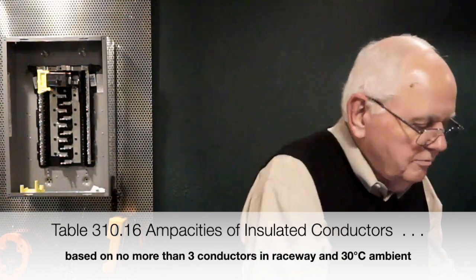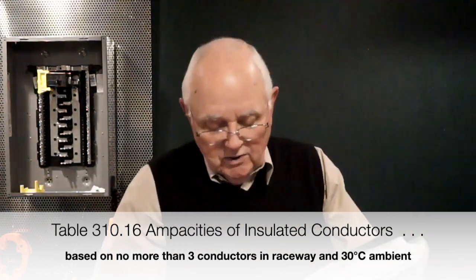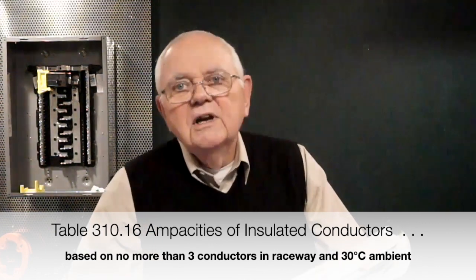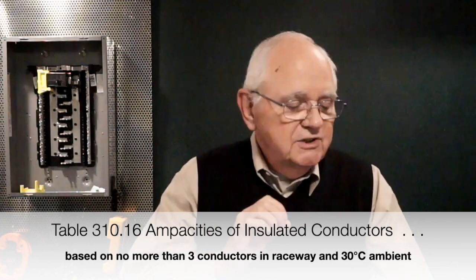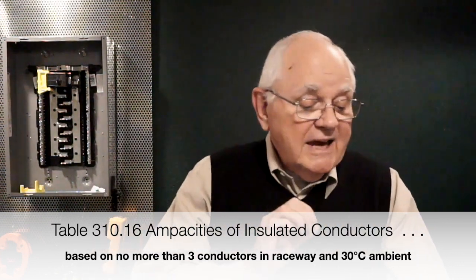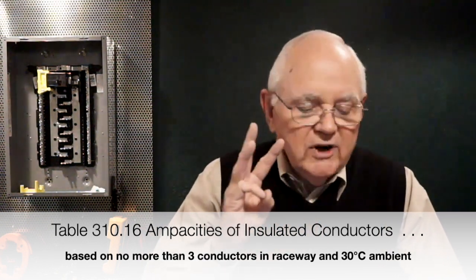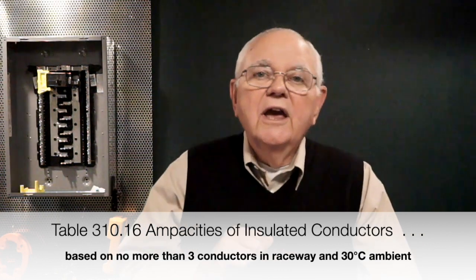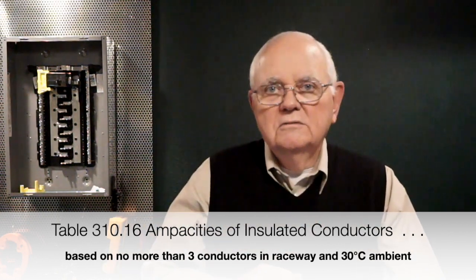And let's talk a little bit about table 310.16. In my 2020 edition of the code book, it's on page 161. Well, the title itself is important. Table 310.16, ampacities of insulated conductors with not more than 3 current-carrying conductors in the raceway, cable, or directly buried in the earth.